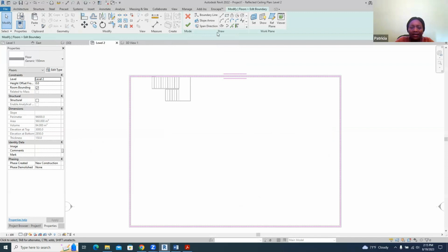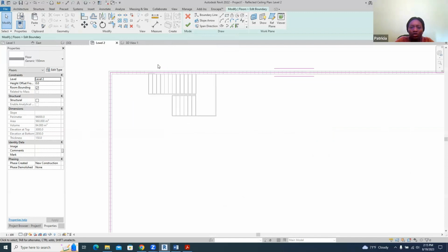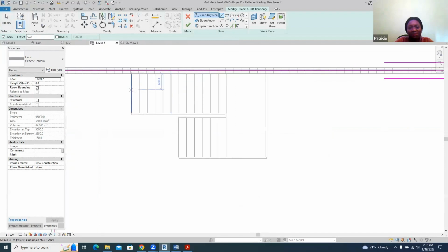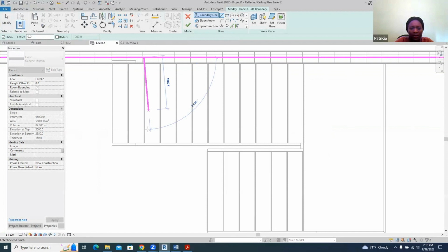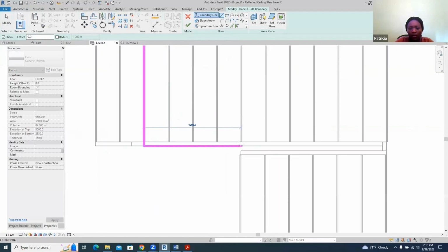This line is the boundary of the slab. Right now we want it to be open where we have the staircase. So I go to line and draw around it. We started climbing from here. Sometimes our slab may begin maybe 3 steps after because we have enough headroom. So we go here, and remember it's going to end at the end of the staircase. So I'm coming here.